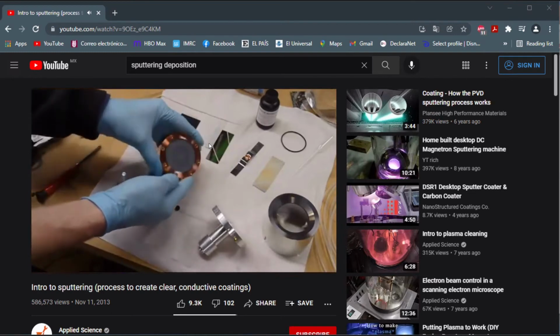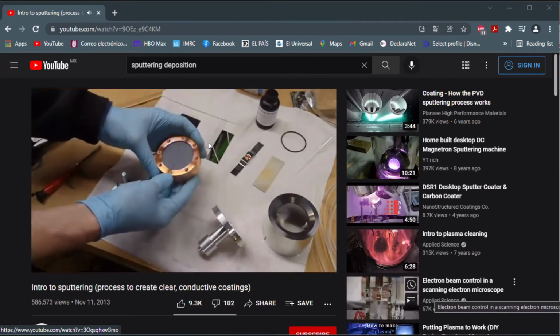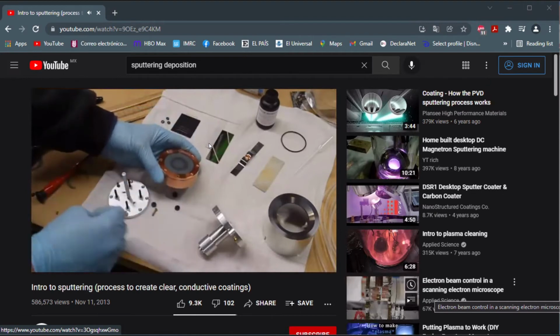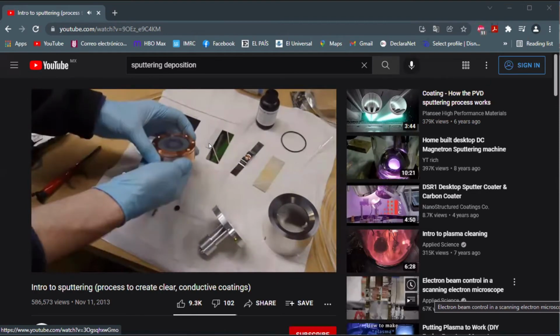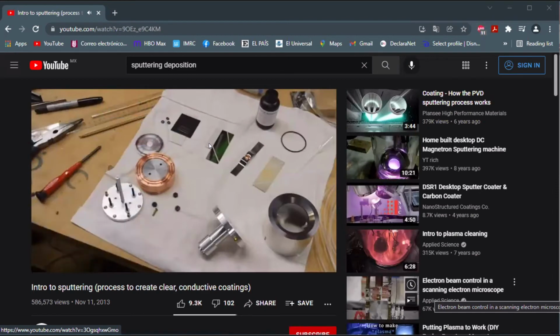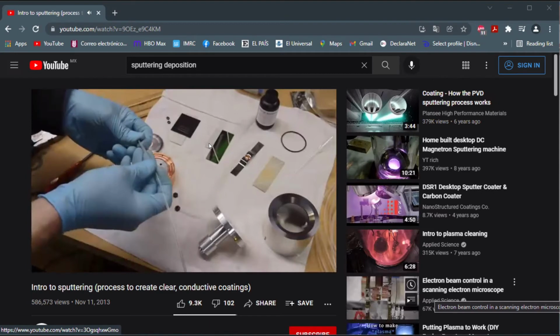And you can even see one that I cracked my disc, unfortunately, so I'm not going to undo the top layer just yet. But also that there's a ring pattern where the disc has been eroded by the sputtering. I've also got some holes in here for a cooling system, which unfortunately I didn't have running yet, hence the cracked disc.